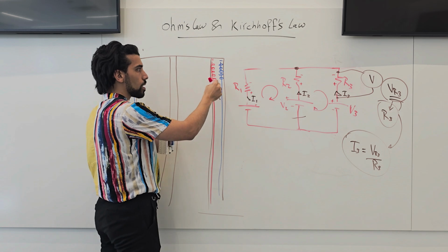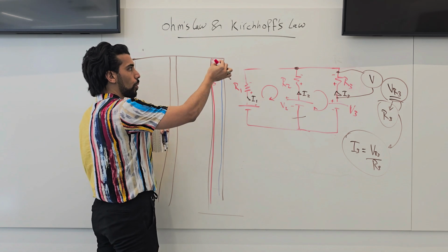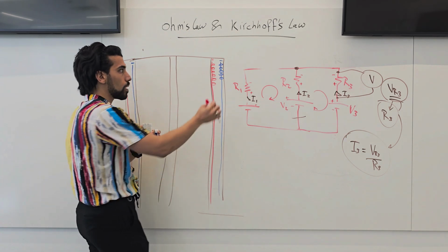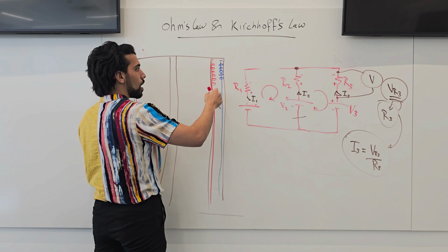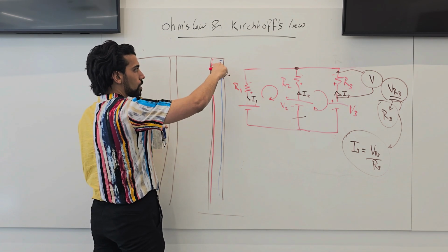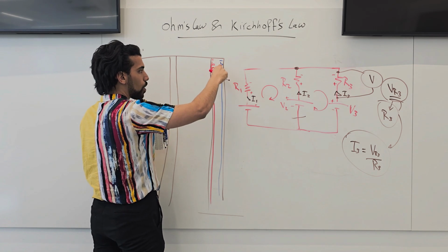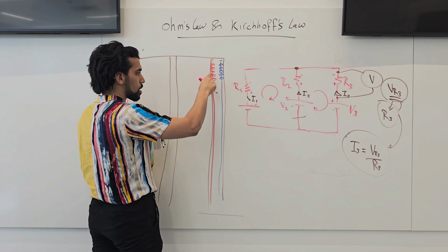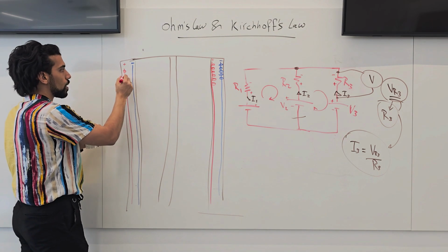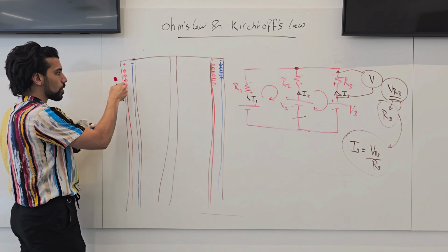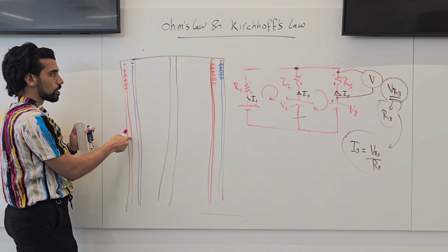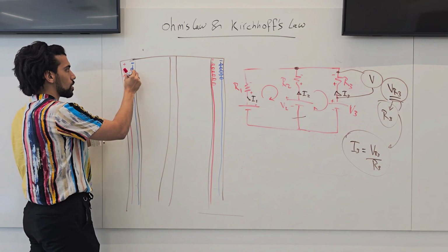These holes are made to insert the electrical components, like the resistance, inside. We put it inside, and all these holes are connected from inside. So basically, all of them are one node. This side, all of it is one node. This line is also all of it one node. All these points are connected to one another, and all of these are connected to one another.